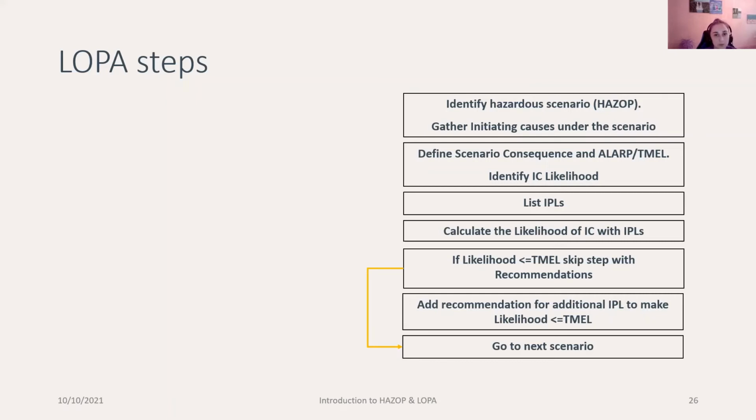So one specific hazardous scenario will be created during the HAZOP, and causes which lead to the same specific hazardous scenario will be added to it. You gather all causes, which are called initiating causes under the scenario.